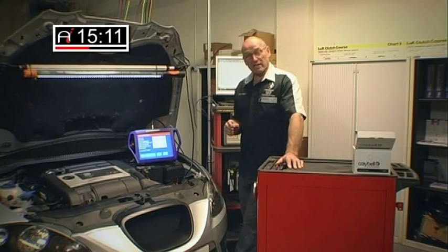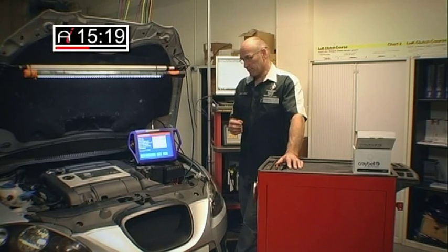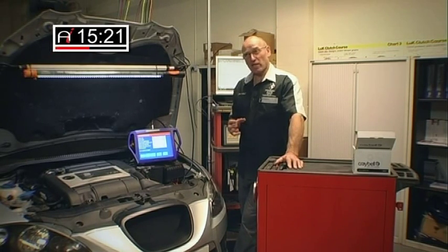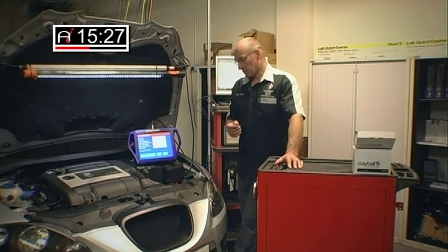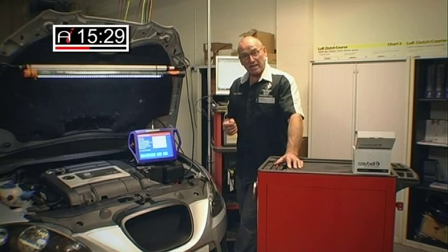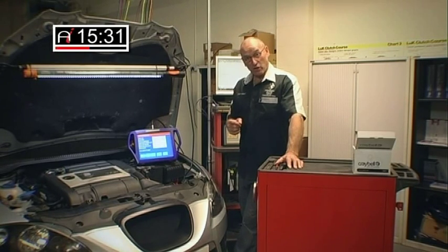That said, what I'd now like to show you is how we actually test the air mass meter by other means. When air mass meters went digital, it presented a challenge. Previously we would compare the analog value, which is a voltage, against lambda and the throttle position indicator, or APP. And that gave us a very nice linear graph which was very easy to interpret.